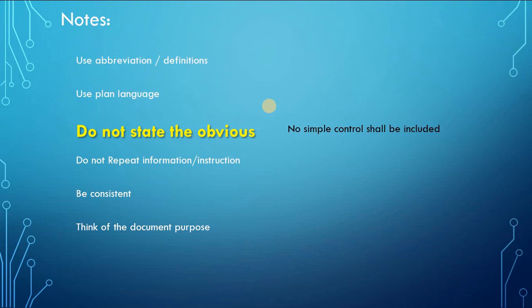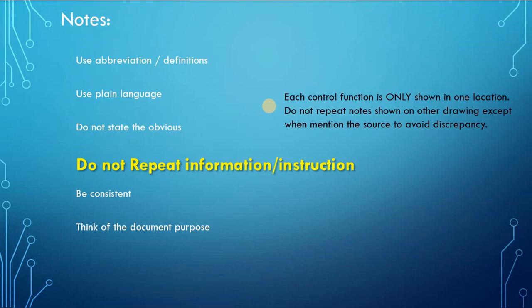Now, the obvious. We're talking about, let's say, PID control. So you don't include the PID control because everybody knows PID control. If your programmer doesn't know PID control, that means we have a bigger problem. So the obvious stuff we agree in the beginning of the document will say logic PID will not be included. Any PID loop will not be explained in the control narrative. We're wasting our time, wasting everybody's time, and so on. So you find this obvious stuff, don't include it.